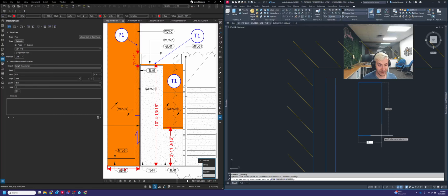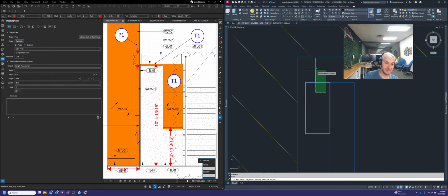It's going to be 0.75 thick by 1.5 tall, like that. You're going to use the move command, and you're going to line it up with the back of your panel just like this. Okay. And the last step is we're going to use the move command one more time, and we're going to line it up with the back of the panel and align with the top of the ceiling.